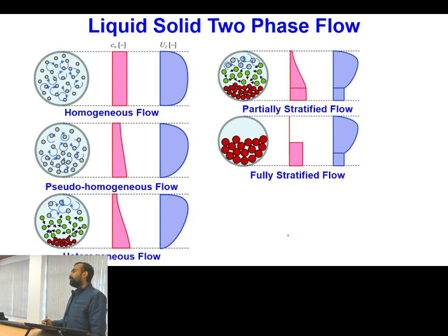So in case of dilute, the particles will be suspended in the fluid medium and the particle interactions are not important. On the contrary, in case of dense phase flow, particles are closely interacting with each other. These are kind of overlapping over each other. So there, particle interactions are important, whereas the gas which occupies the void spaces between the particles is not important.